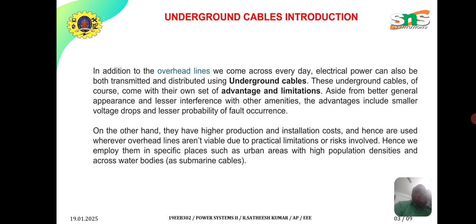Underground cables introduction. In addition to the overhead lines we come across every day, electrical power can be both transmitted and distributed using underground cables. These cables of course come with their own advantages and disadvantages. Aside from better general appearance and lesser interference with other amenities, the advantages include smaller voltage drops and lower probability of faults.